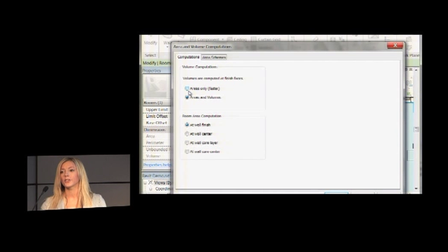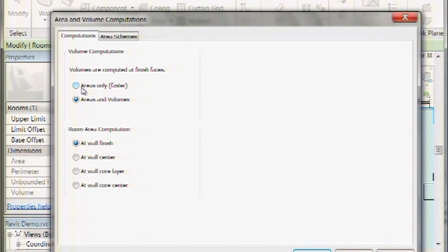If you're looking at a 3D view, that's going to cause it to run really slow. So a lot of people, architects you deal with, are going to put this on areas. So when you open it and you see that there's an issue, it doesn't look right, make sure it's turned on here. This room and area computation is actually quite deceiving, because this purely means the way that it looks at things like tenant space or other details inside of Revit for its takeoffs.